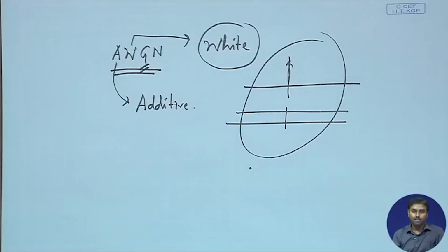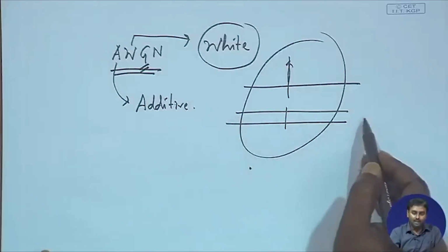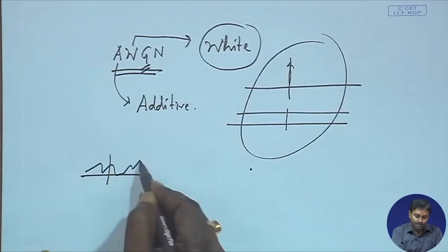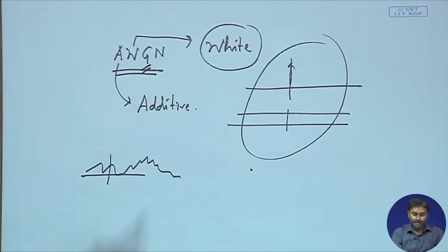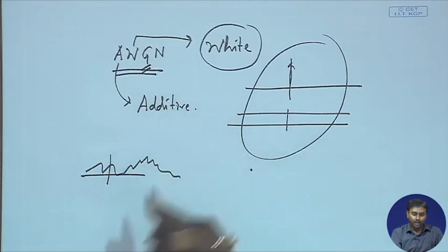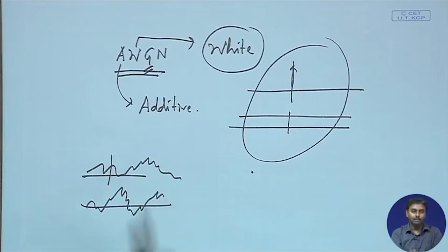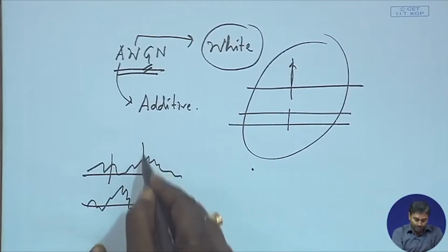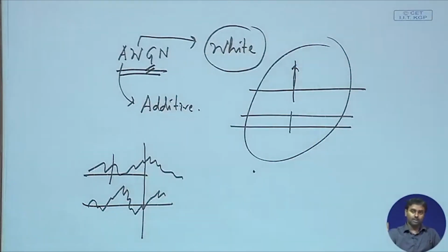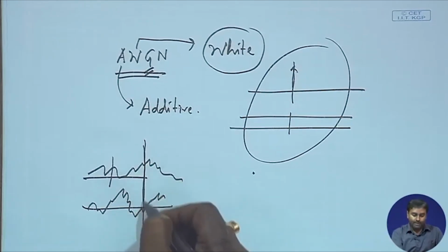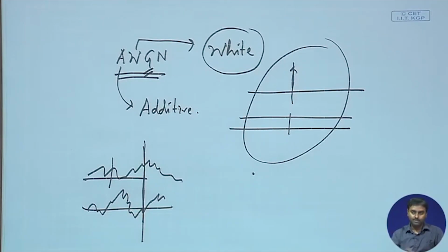The next part is G, which is Gaussian. Okay. So, what does this mean? See, this is the power spectral density, this is the autocorrelation. The actual noise will look something like this, right. And because it is a random process, you can have different such samples, an infinite number of such samples which will look different if you take different samples. Fix any instant, it is a stationary process, we have already talked about that whatever that noise is, it is already stationary. Okay. So, any time you pick, I know that the statistical property does not change.